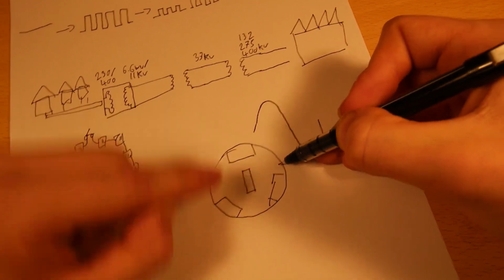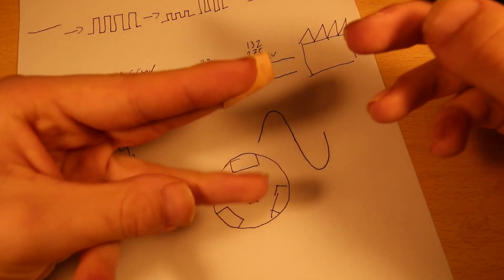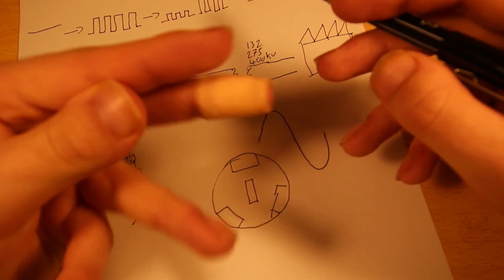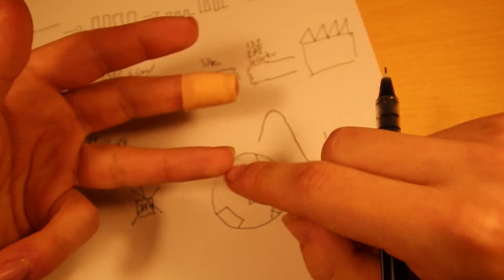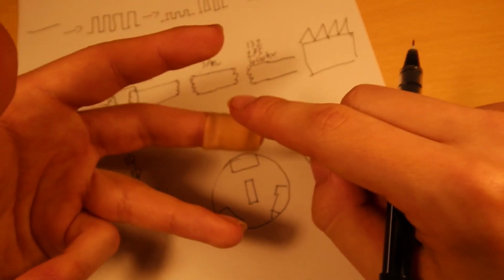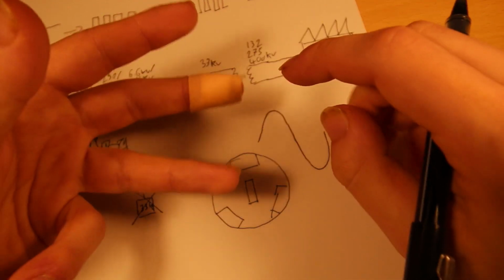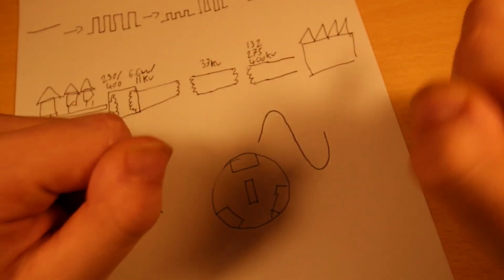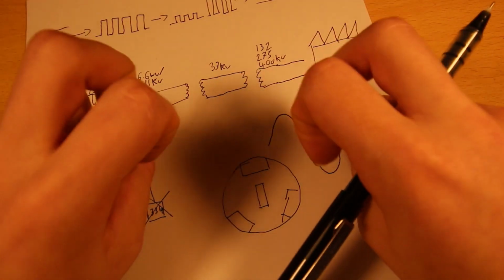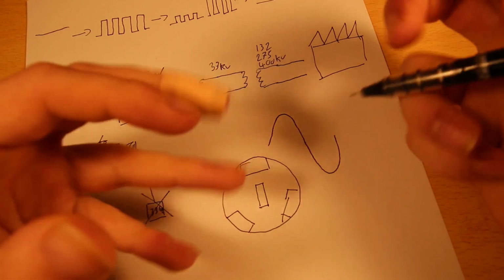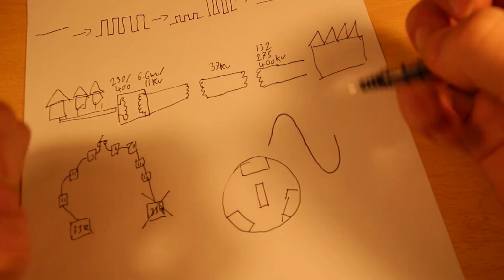I said there were 3 coils, and some of you might be thinking, well, that's because there are 3 wires in a mains cable, there's 3 pins on my plug, but that's not how it works. The 3 pins on your plug are a line, a neutral, and an earth. Those go by different names depending on where in the world you are, but I'm going to call them that because that's what we call them in the UK. These 3 windings here produce 3 phases. 3-phase power is not used domestically much. It's mostly reserved for industrial purposes.